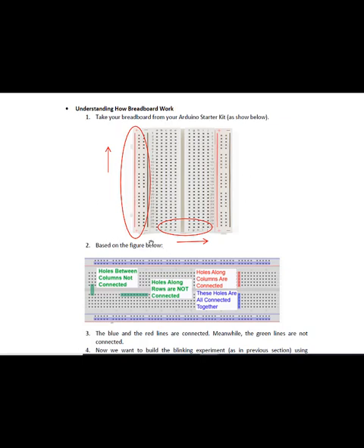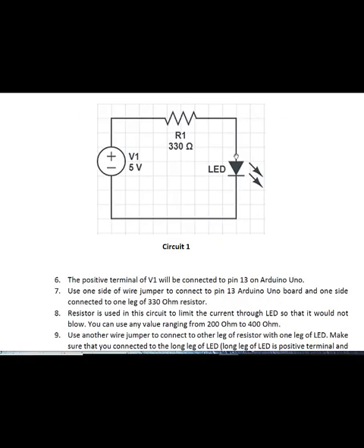Alright, so this is the breadboard, and it will be used to assist you for the connection between your equipment to the Arduino board. Now, let's try and do our first Arduino program. The main purpose of this project is to light up the LED, the red color LED, which I will show you afterwards. We need to use several pieces of equipment, which include the resistor of 330 ohms, together with the LED and also the Arduino board.